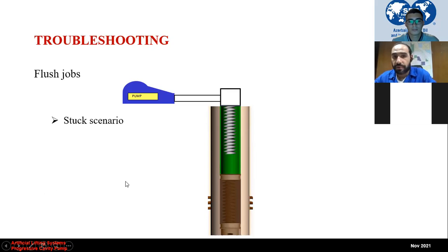As we said, the rotor is normally rotating inside the stator. When huge sand comes in between, this will be translated to high torque. If monitoring is going fine, you will easily catch this on the VFD. Unfortunately, in some cases, bad monitoring will discover the situation very late. So in this situation, the rotor will become completely stuck inside the stator.